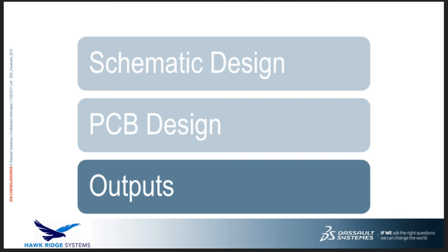I will show you the ease of configuration for all manufacturing outputs for the bare PCB, schematic bill of materials, assembly files, drill files, everything necessary to create the assembled PCB and PCBA.